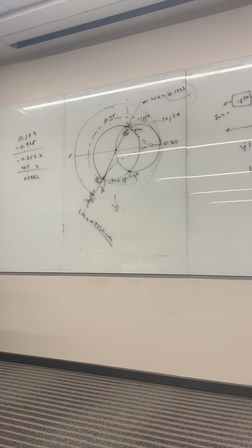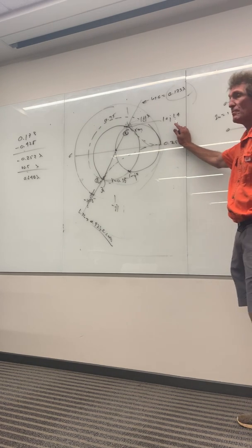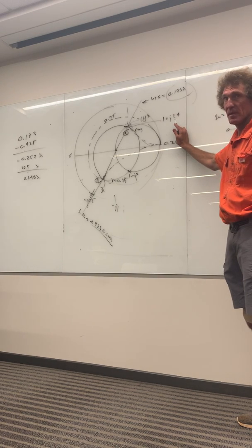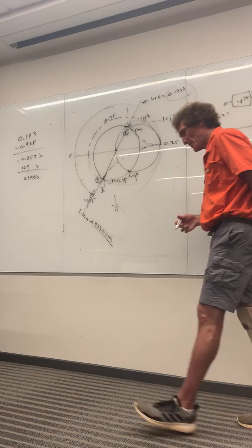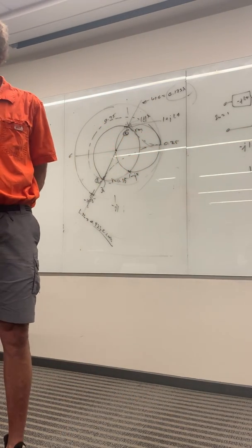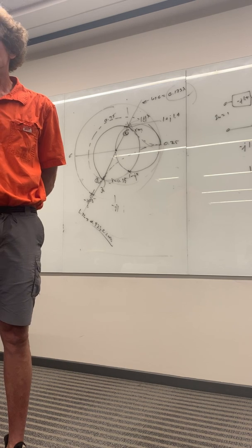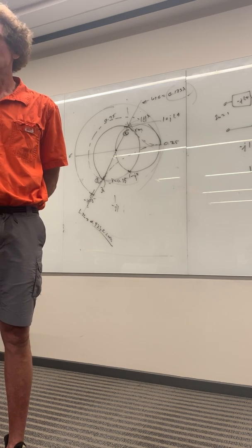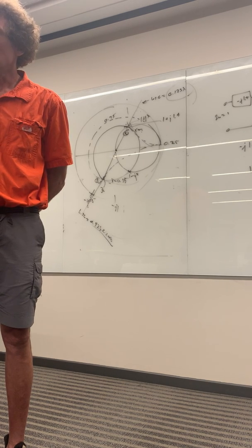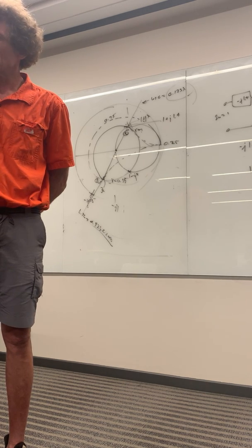Y'all see what I've done there? Remember, the whole deal is, once I have that J 1.4, I have to add something in series to get rid of it. And what am I gonna add? I'm gonna add a minus J 1.4, which boils down to a capacitor. The normal capacitor reactance is just 1 over J omega C. Since we're talking about normalized impedance, I have to divide that by Z naught. Do you agree with me, everyone?